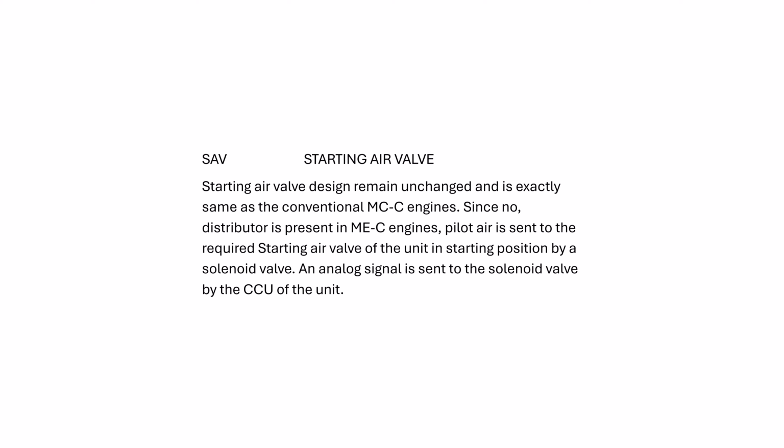It gets an analog signal. The solenoid valve will open and allow the air to start the air to the starting air valve. What was done by the pilot air, which is coming from the distributor. That is the only difference. All right.